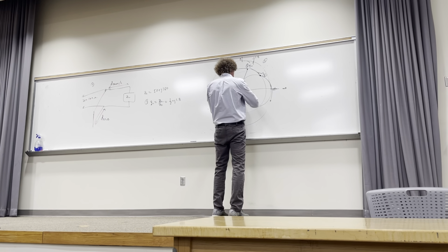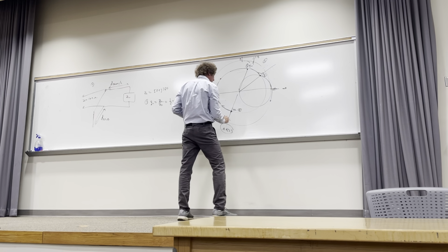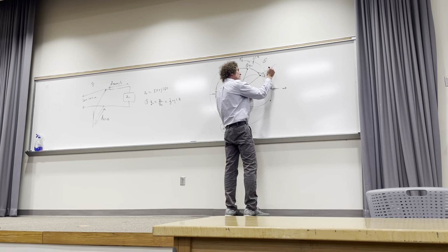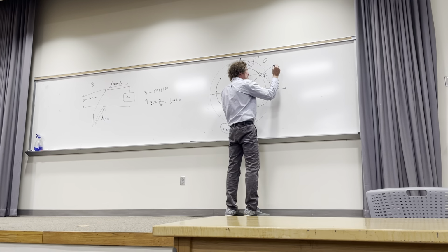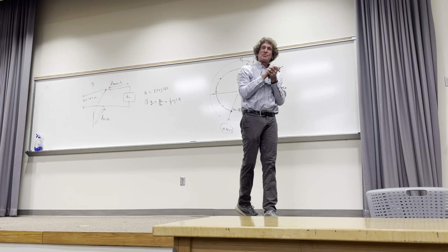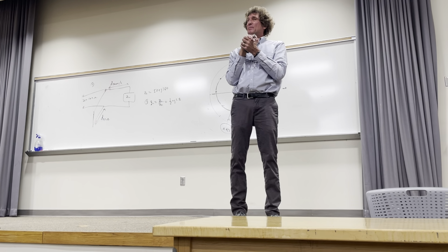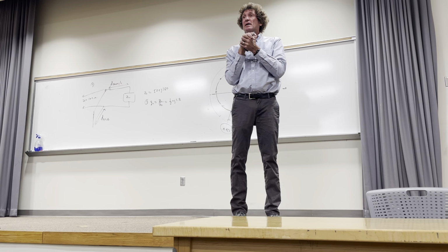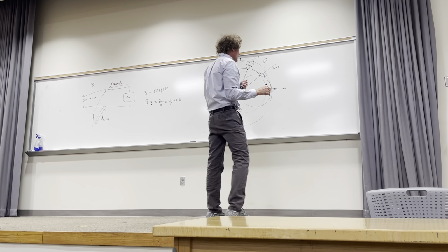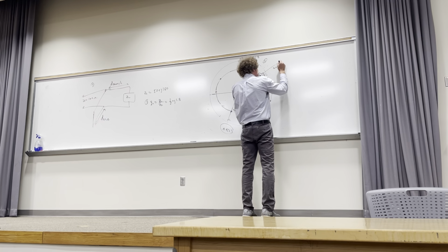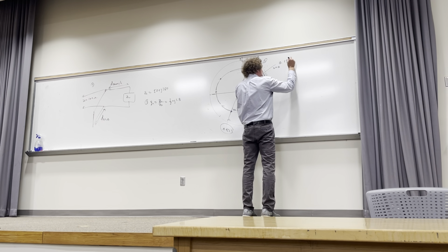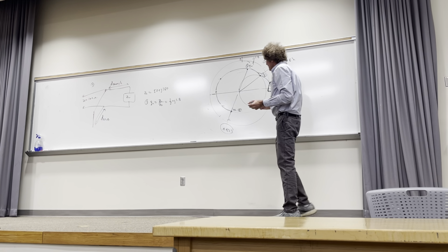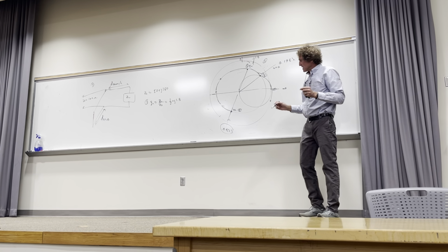Now you shoot a line through here, and you'll see that on the wavelengths towards generator point, I forgot if it's 0.178. Can somebody just tell me what that outer point is, wavelengths towards generator? Say again? Sure, 196. 196? Somewhere in there, yeah. So this is 0.198 lambda.